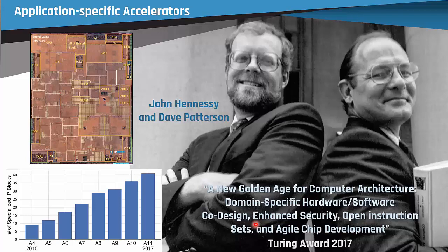I mean, we did a lot of things since then, right? We have dynamic voltage and frequency scaling. We have all kinds of things, shutting down cores, big little architectures. There's lots of ways to try and cool things down. Okay, you can go into turbo and raise your voltage just for a second and then put it back down when you finish your computation. You can do other things like on GPUs, they have actual liquid air conditioning type things, but they don't want to do that on your laptop, right? You don't even want to have a fan in your laptop for that. And for sure not in your phone.